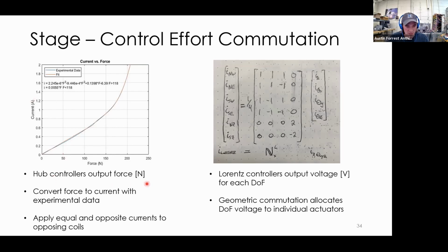It's also interesting here, I can basically set the units of my controller effort as whatever I want and then use the gains of my loop to sort it out. So if I set this output as force, then in my model, I'll just say that my controller is directly acting as a force on the plant rather than going through the voltage to current conversion and everything, and the units work themselves out, which is pretty cool.